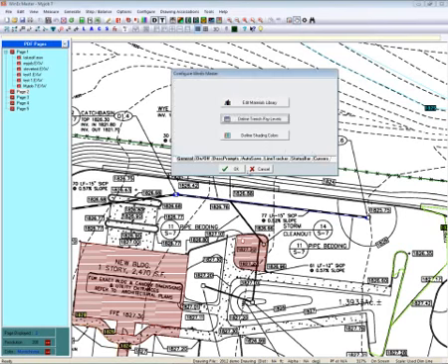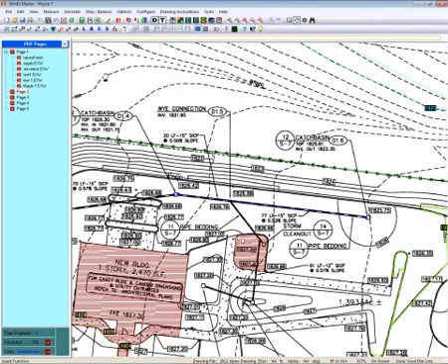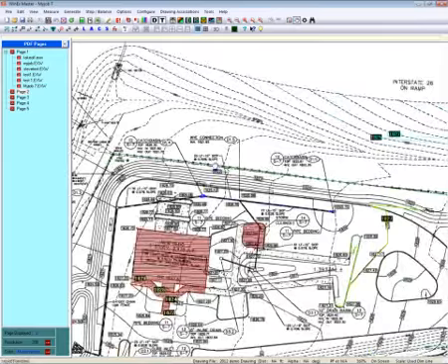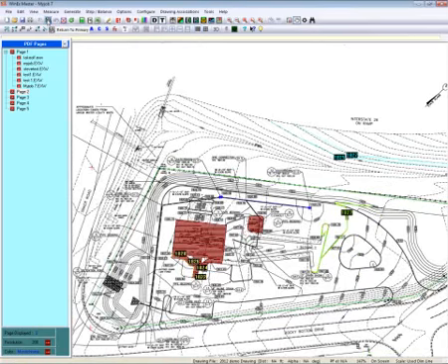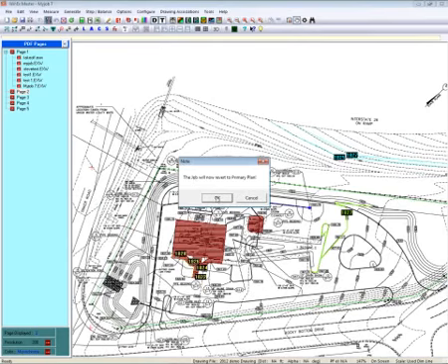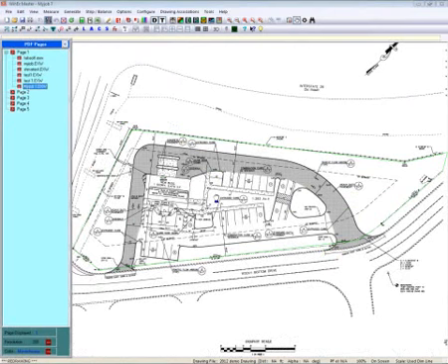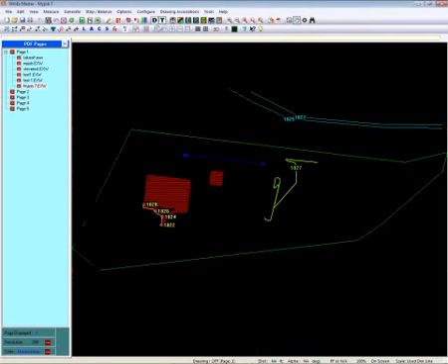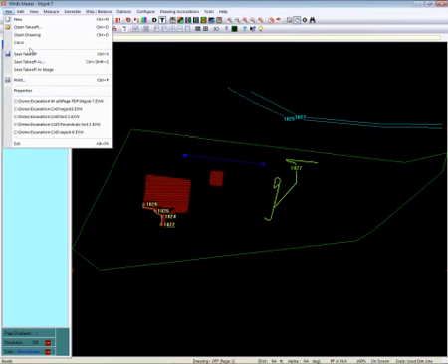Now, for the sake of time, I'm going to close out of this. We'll go back. I'm going to take everything we did here, and we're going to go back to our first page. So we'll go back up to alternate plan, but now it says return to primary. So we'll do that. And here we're back on our first page. If I turn my drawing off, you can see everything we did on that second page now sits perfectly scaled on this page. And if I close this, which I'm going to do very quickly,